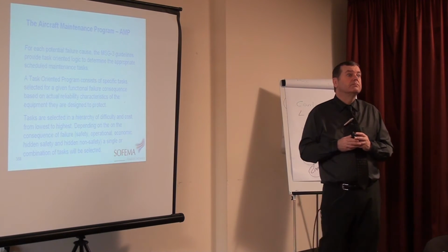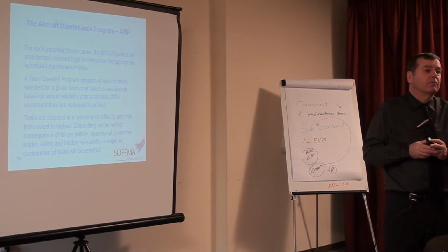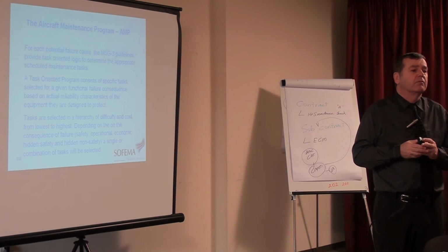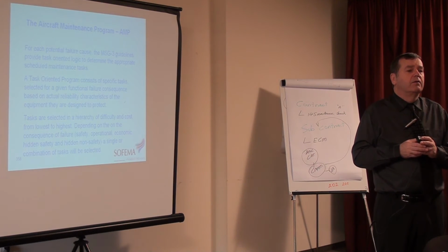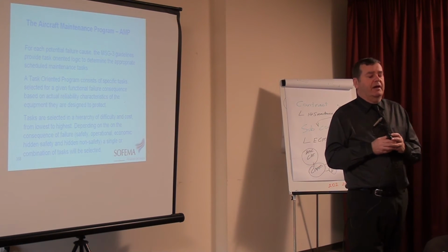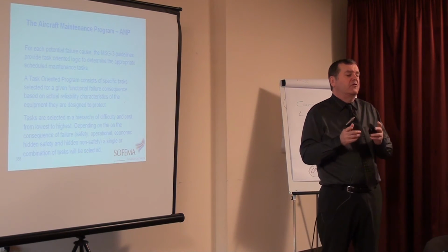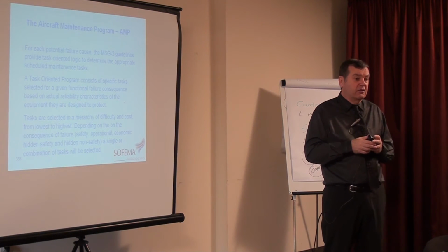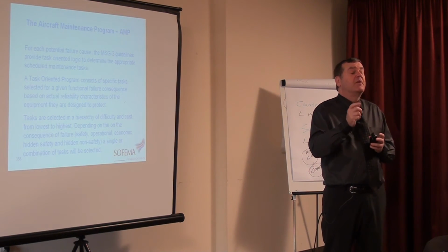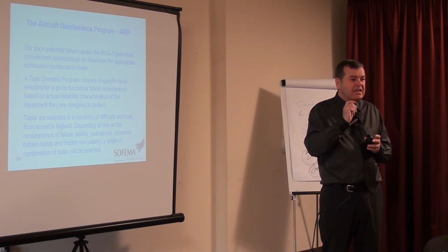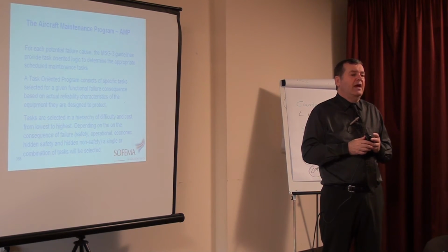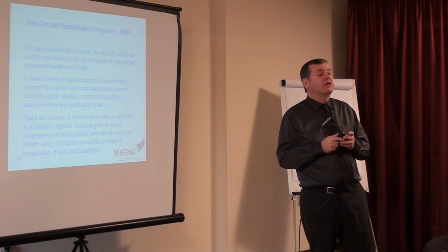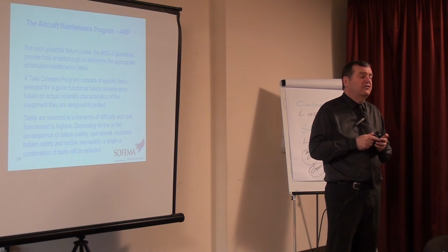So, like those tasks, must a defect be tied to the area? Like when you defer an item. So, when we talk about defects, this is something different to the task in the maintenance program. The task in the maintenance program is a requirement to perform a maintenance action. When we have a defect, we have to resolve that defect before the aircraft flies. And I use the word resolve intentionally because I didn't say fix, I said resolve.